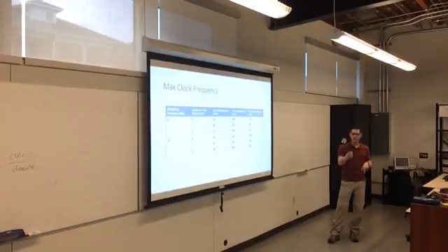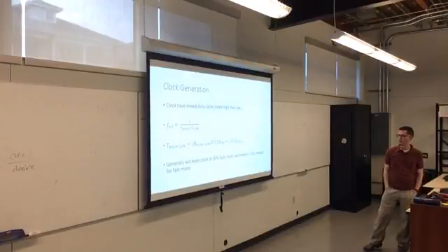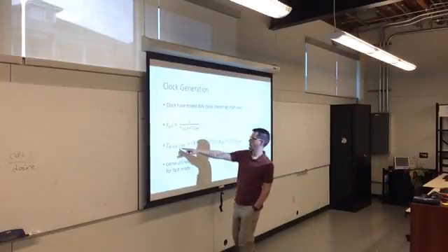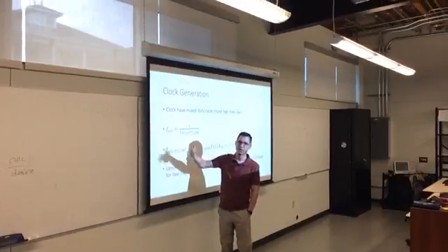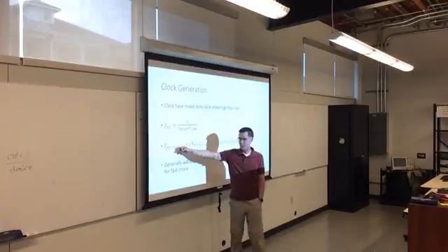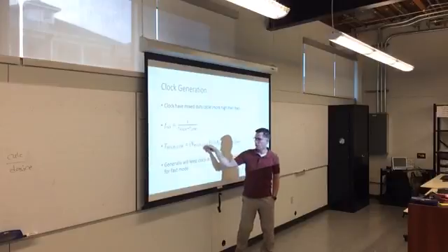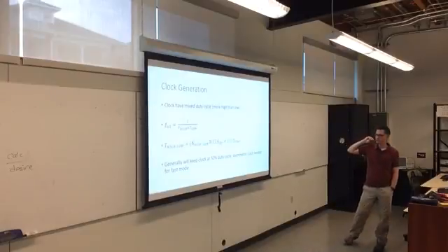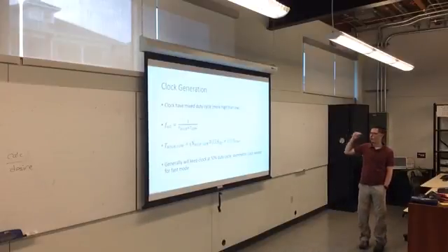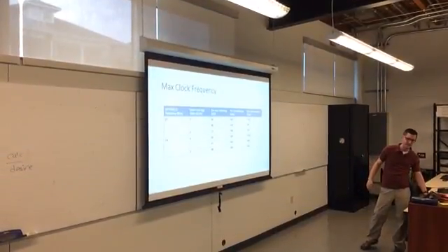Travis? So on the previous slide, yeah. So it is T high plus T low and then T high over T low? No. This is a subscript. So this is how you calculate the clock frequency, and if you assume that they're the same, that there's a 50%, then T high and T low is calculated by this. So like this is the rate, this is a ratio factor of high to low, and then that gives you either high or low. So in our case, N high low would be 1 or 50, or you have to look at, let's see how you do the calculation. Yes, it's just 1. Like there's no real ratio there.